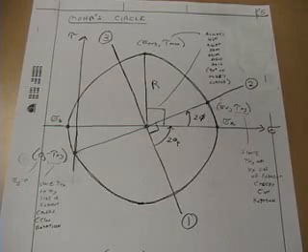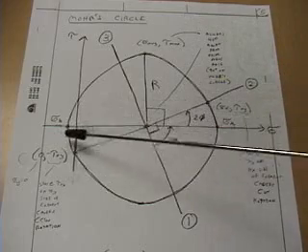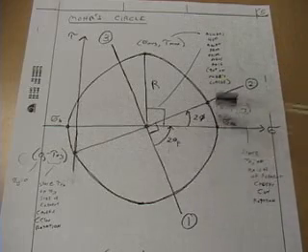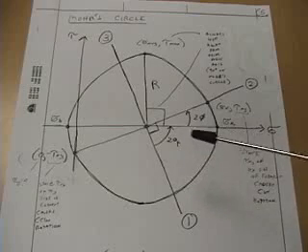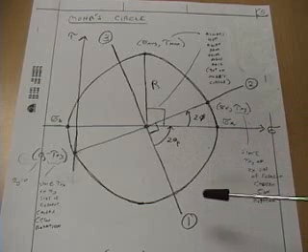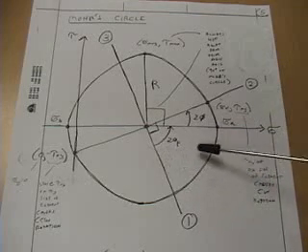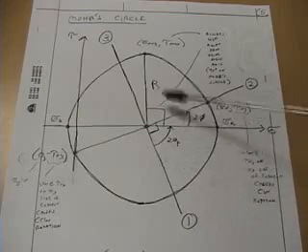Mohr's circle allows us to visualize all of the gauge directions, the maximum and minimum principal stresses, and all of the angles involved in this analysis. First, we can see the gauge directions. Because they are oriented 45 degrees apart on the top of the bar, on Mohr's circle, all angles are twice physical angles, so you can see they're 90 degrees apart on Mohr's circle.